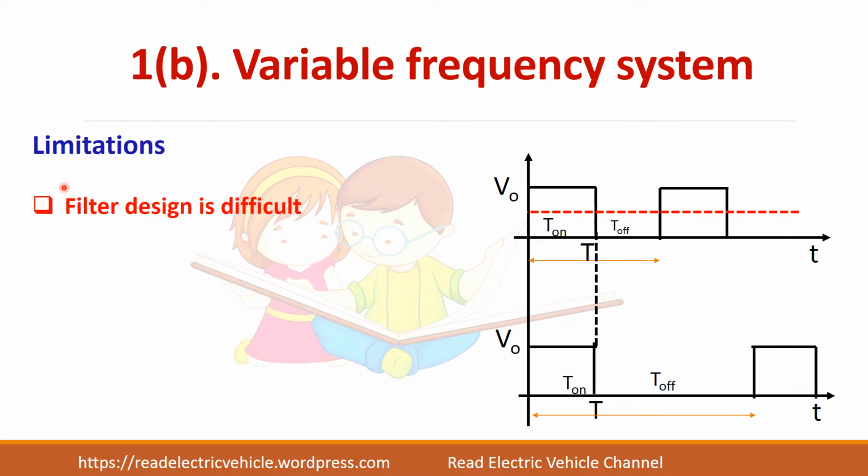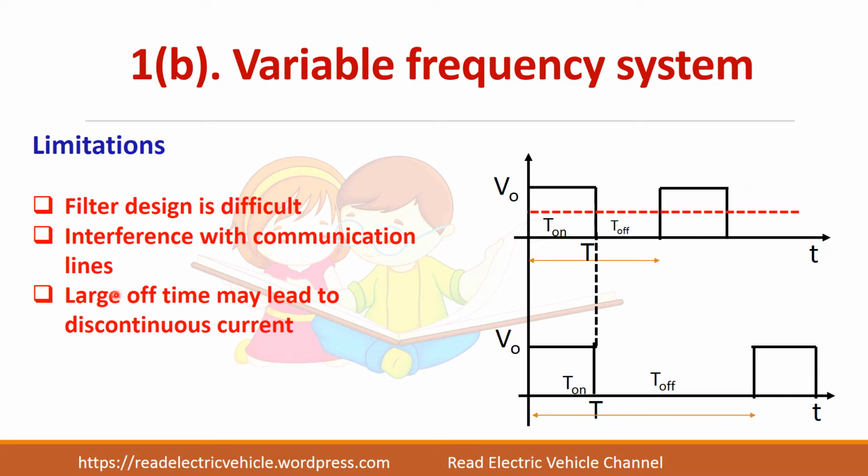So we will see the limitations. First thing, filter design is difficult, and since we keep on changing the frequency, there will be interference with the communication lines, and sometimes if you have a large turn off time, this will lead to discontinuous current.